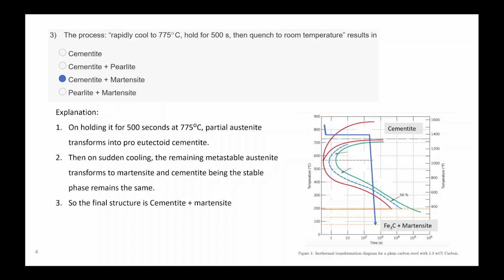If yield strength is very high for a material, then it acts as a brittle material. So it won't absorb much energy, and it will break very fast. So it will have low impact toughness if it has higher yield strength. That toughness is different from the toughness that you measure using very low strain rates. So if the yield strength is higher, then the impact toughness will be lower.